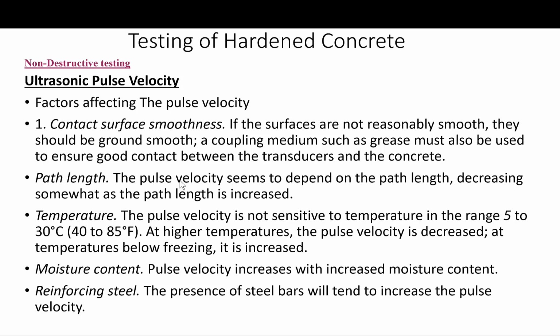Anyway, in spite of these difficulties I just named, pulse velocity measurements are used regularly as a means of assessing concrete quality. They are used to study uniformity or for quality control, estimations of strength, setting characteristics, durability, and the extent of cracking in a member, as well as to determine the modulus of elasticity. I used it extensively in my work and in my research, and it's a great tool. Again, as long as you're careful when you apply and interpret the results, I think you'll be fine.